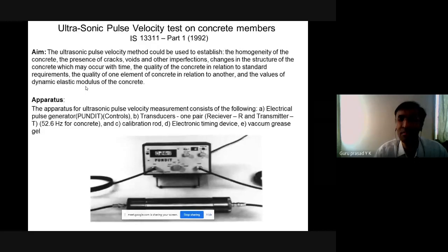We have seen that sometimes they pour more water. That is, the water cement ratio gets affected in those cases. And when we put more water, the strength of the concrete comes down. Whereas we have to design the concrete member for M30 or M40, when they pour more water inside, and mostly it happens, the concrete strength comes down. Whereas the particular column had to be designed for M40, it ends up becoming like M32 or M31.